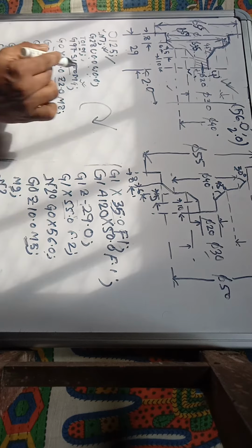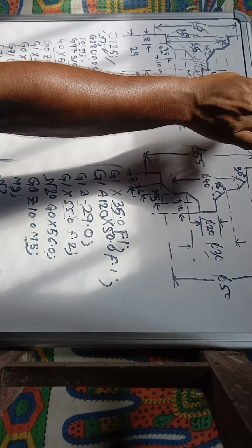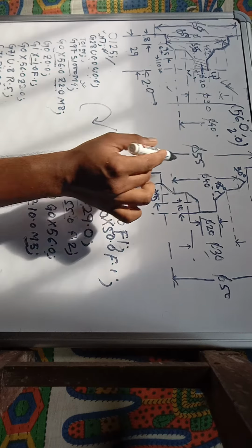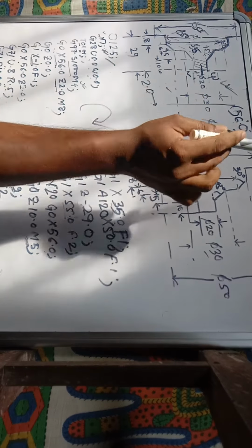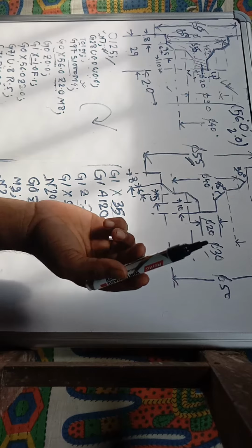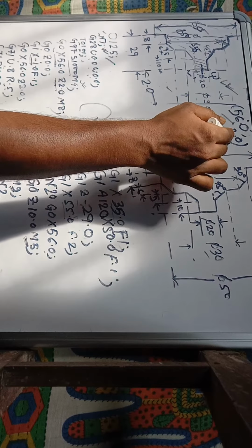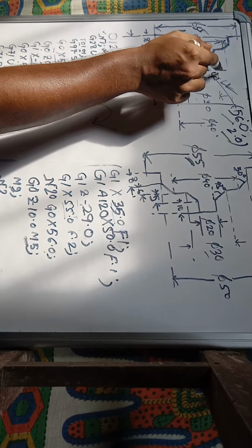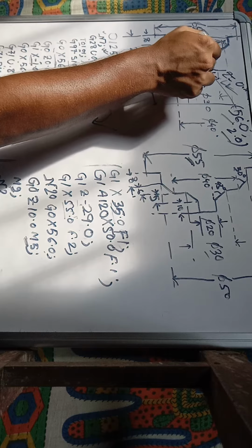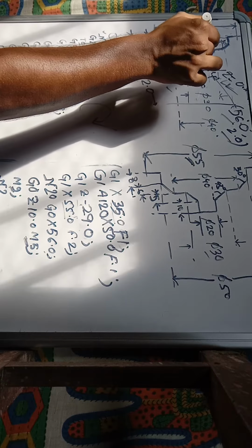Suppose X56.0 Z2.0: this is the coordinate, 56.0, and the maximum diameter of the job is 55. So we will move the turret, I mean the OD holder, from home position to this coordinate X56.0 and Z2.0. After that we will move the tool near the job to the face, Z0.0, which is also written here. After that we have to face the surface, because the face is not clean, we have to clean the face.